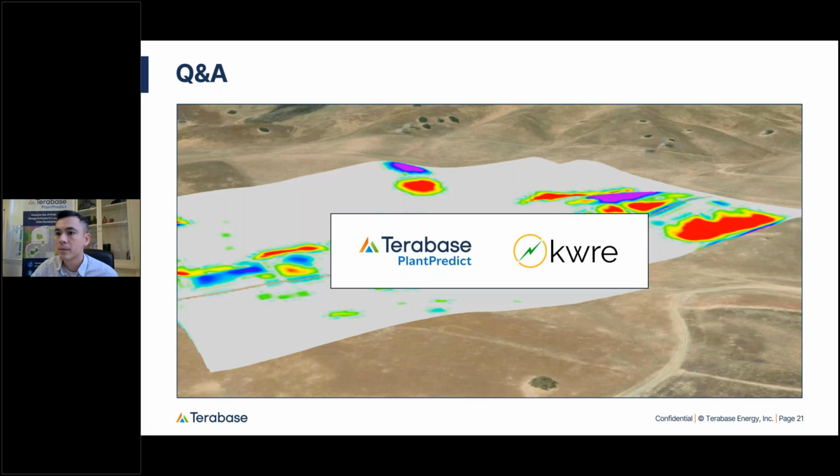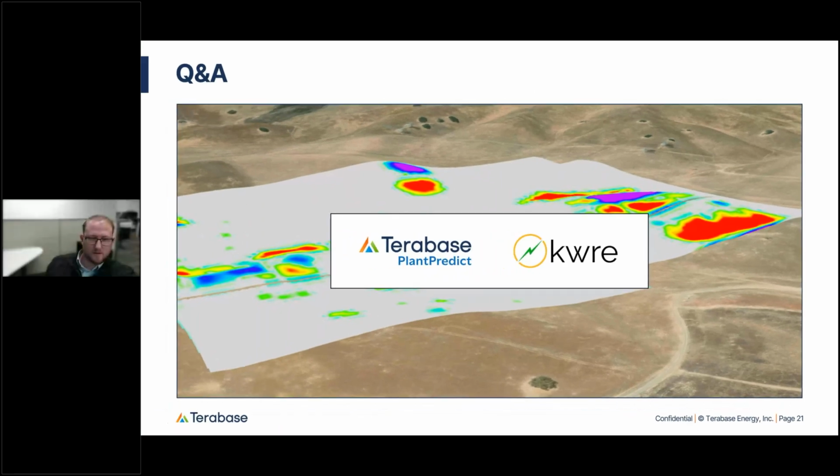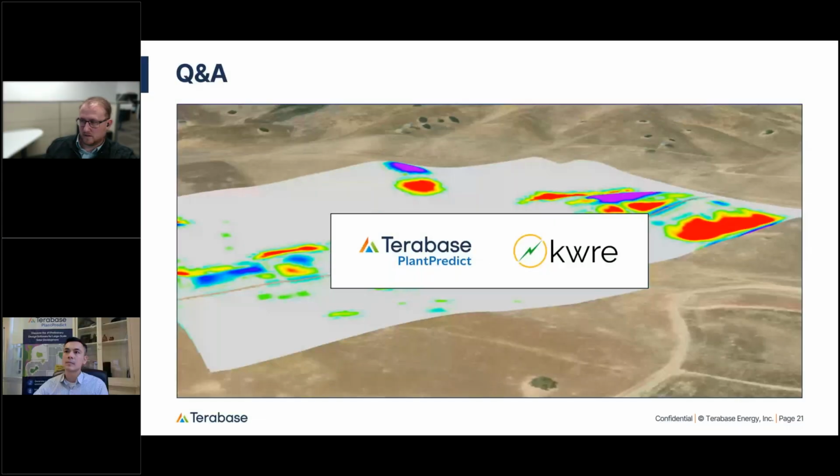Tang, could I add a note there too? Sure, yeah, please. So what I demoed there was a 1 foot contour interval, but if I wasn't trusting those 1 foot contours, or maybe had good enough data that I wanted to go deeper than that, I could export from CAD a half foot contour level or a 0.1 foot contour level, to whatever detail I wanted, into the Terrain Pro software to fine tune that even further. Yeah, that's a great point.